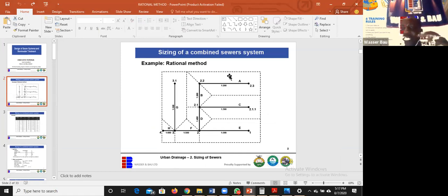So gentlemen, can you see the difference? For the sewer, we got 150 mm for the foul sewer line, for the wastewater line. But when it comes to stormwater, we are getting 700 mm. That's to tell you how huge it is. Most times, stormwater can be up to 90 times the value of sewer. And that's why it is very critical. That's why it can cause flooding sometimes. So the next thing we're going to do is the storm for catchment.